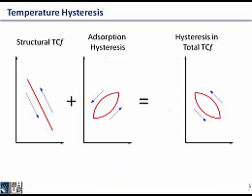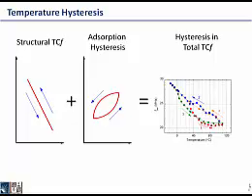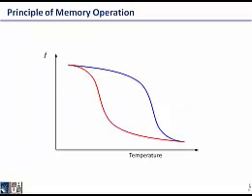So there are a few different mechanisms that could contribute to that, and we are doing some experiments trying to fully understand it. But with that said, we're also thinking, what can we make use of this hysteresis in these NEMS resonators for? It turns out that when we have a hysteretic loop, we can turn that into a memory device. So here I'm going to very briefly illustrate how a hysteresis loop can be leveraged to make a memory operation.